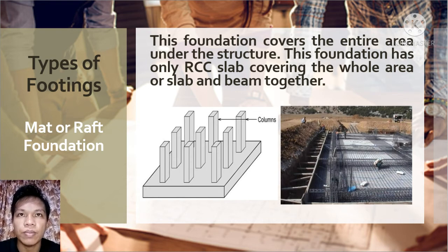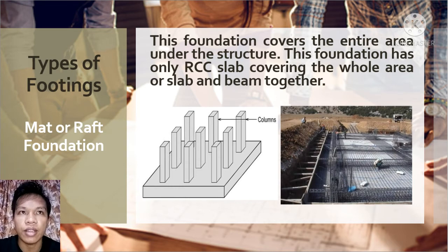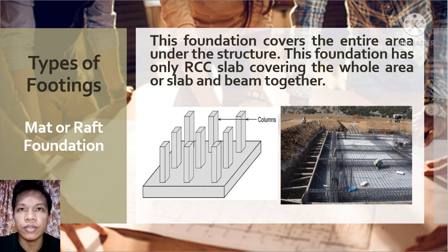Mat or raft foundation. This foundation covers the entire area under the structure. This foundation has only an RCC slab covering the whole area, or slab and beam together. Raft foundation is adopted when heavy structures are to be constructed on soft, made-up ground, or marshy sites with uncertain behavior.